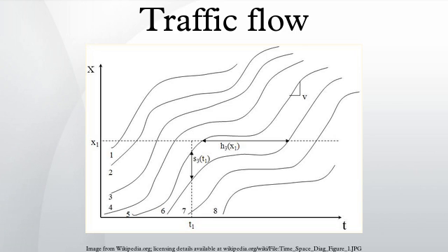If speed is measured by keeping time as reference, it is called time mean speed. If it is measured by space reference, it is called space mean speed. Time mean speed is measured by taking a reference area on the roadway over a fixed period of time. In practice, it is measured by the use of loop detectors. Loop detectors, when spread over a reference area, can record the signature of vehicles and can track the speed of each vehicle. However,